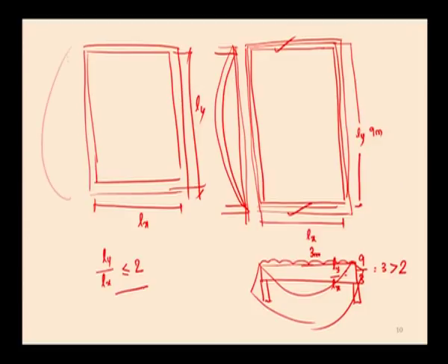It means that the slab has to be supported along both the directions on all 4 walls, understand. So, it means that there is a deflection along the longer direction and also the deflection along the shorter direction. The deflection, or the bending, along both the directions has to be considered, and the bending moment has to be found along both the directions by taking the section along both the directions.